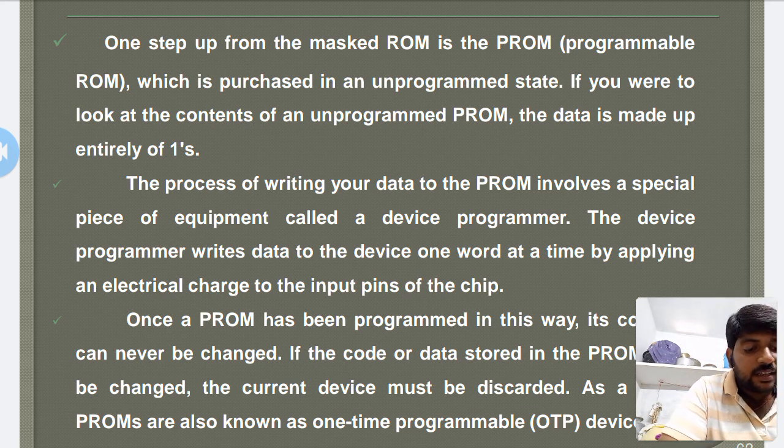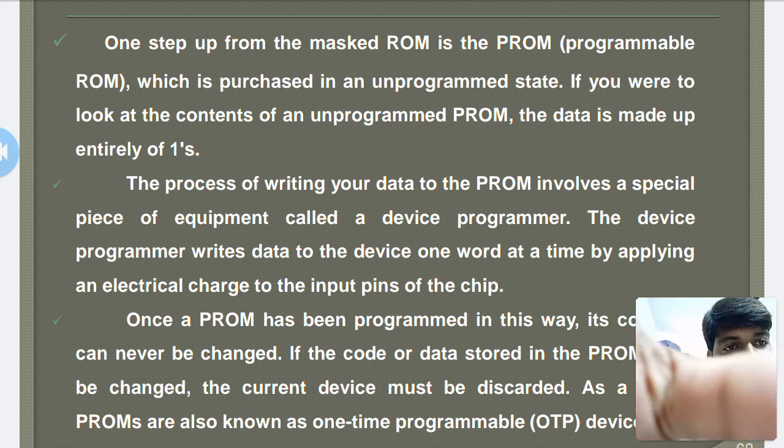The memory has nichrome or polysilicon wires arranged in a matrix. These wires are functionally used as fuses. It is programmed by a PROM programmer, which selectively burns the fuses according to the pattern to be stored. Fuses that are not burned represent logic 1, and fuses which are burned represent logic 0. The default is logic 1. So this PROM is for the user-end purpose.